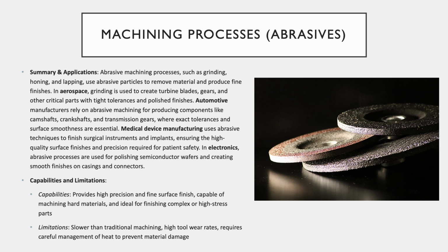The capabilities are that it produces high precision and fine surface finish, it is capable of machining hard materials, and it is ideal for finishing complex or high-stress parts. The limitations are that it can be slower than traditional machining, has high tool wear rates, and requires careful management of heat to prevent material damage.